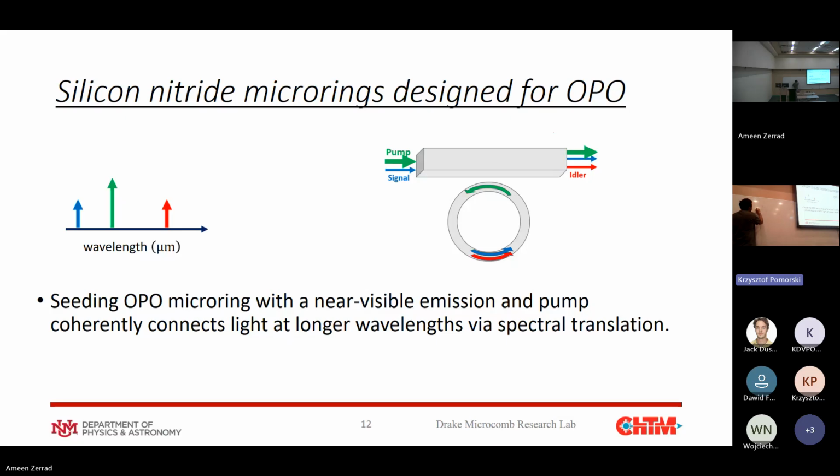So you have your ring height, which I'll just call RH. You have your ring width, which I'll just call RW. So the ring width is anywhere between 650 and 790 nanometers. Your ring height is fixed at 70 nanometers. You can't really change that, and I can tell you why later. But the bus waveguide, we're not so concerned with it matching the cross section of the ring resonator. We fix it at 600 nanometers.